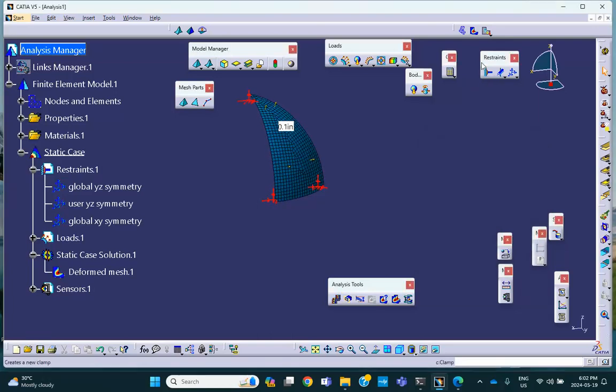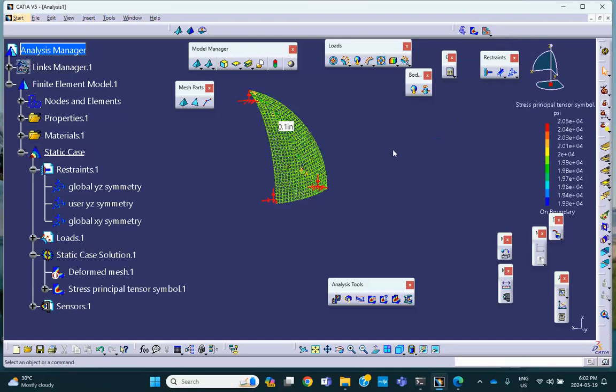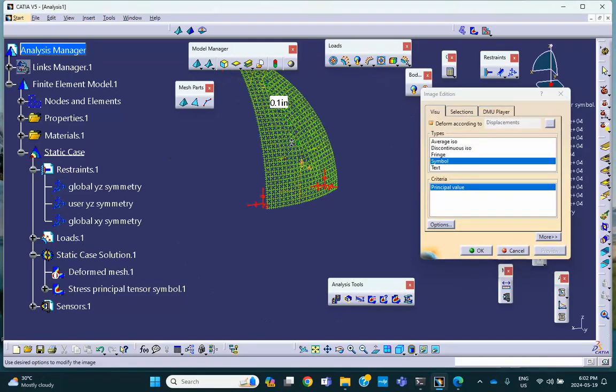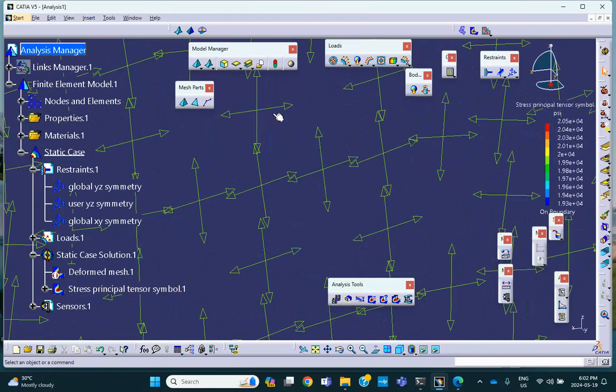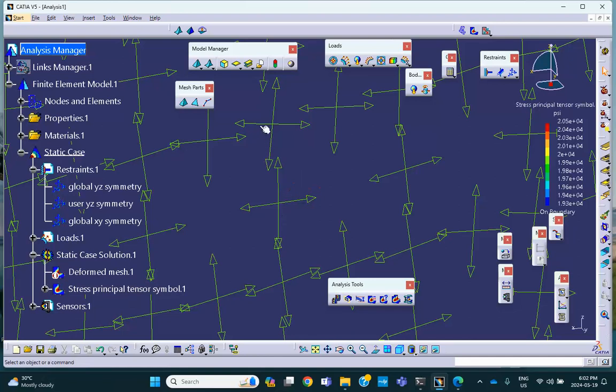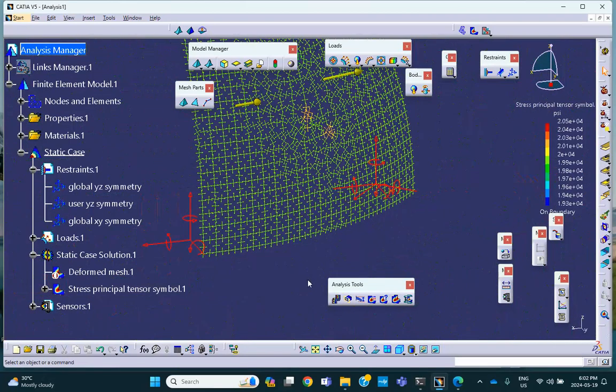All right, folks, and you can plot the stresses here. If you look at the principal stresses, if you zoom in, you know what's happened. Both of them are PR over 2T. In fact, if you zoom in and you put the cursor on any one of these, they must be almost the same number, and they are, because both of them have to be PR over 2T. And if you put the P 100 over 2T, you're going to get this number. All right, folks. Good luck.